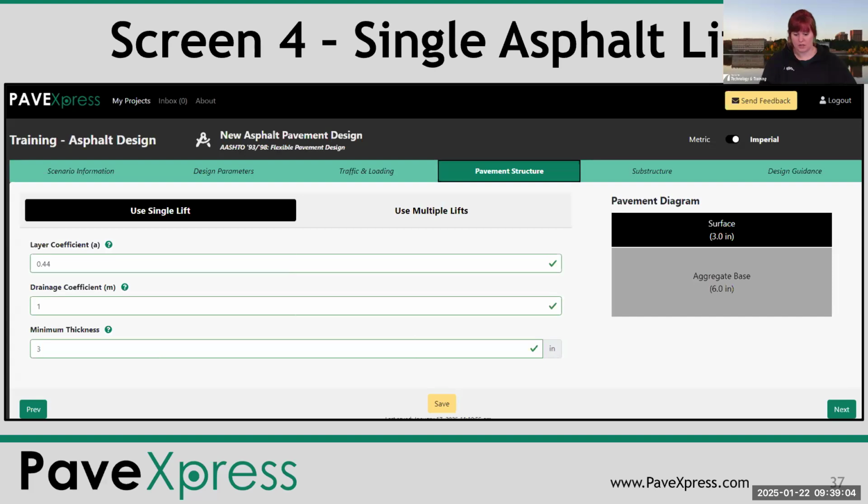I've got a couple of questions. One of which is, does this software offer recommendations for replacements, or is it strictly for new pavement, like full road construction? For replacements, like for a mill and fill? Yeah, that's going to be the second part of the presentation here. You can do an overlay design here, and I've got a bunch of slides on how we go through that as well. But right now we're focusing on designing a brand new pavement. What are my thicknesses?